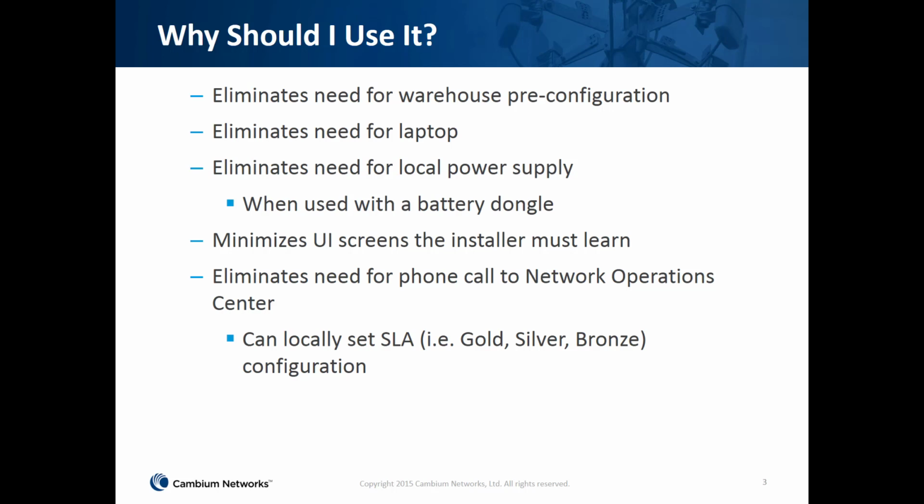It can eliminate the need to pre-configure, and rather than carrying a laptop outdoors during your installation, it eliminates the need for that. And when you use it with the dongle, a third-party battery-powered PoE Wi-Fi dongle, you can get your SM installed and verify that the installation is good before taking time to run your cabling and do the final electrical connections, etc.